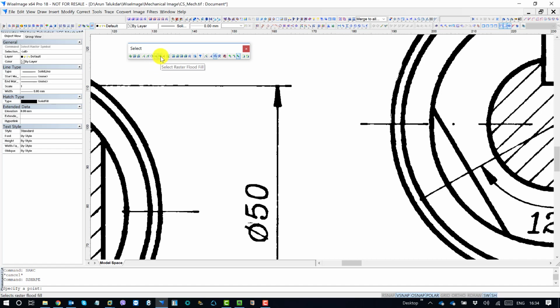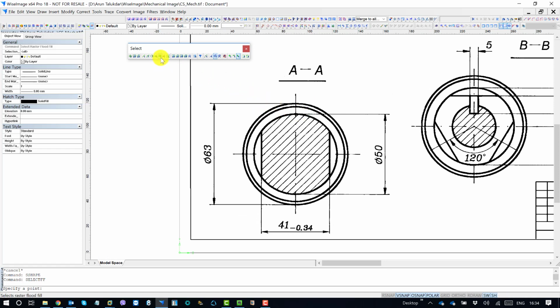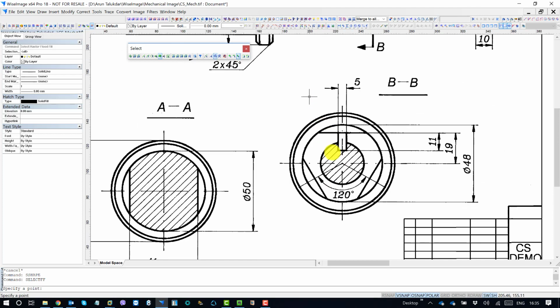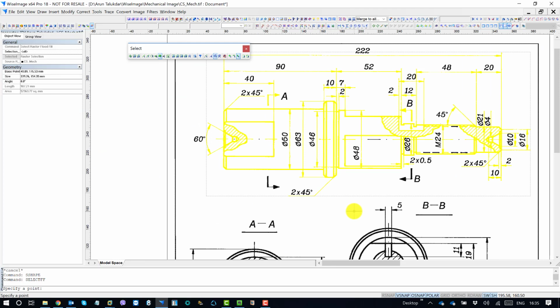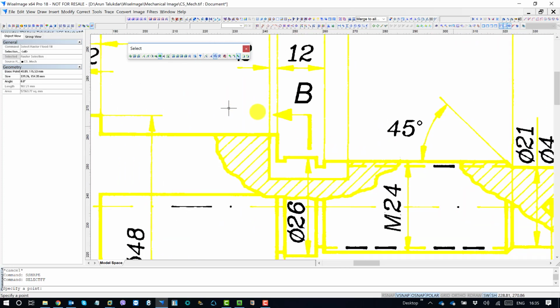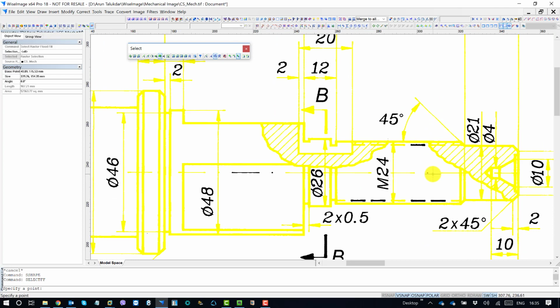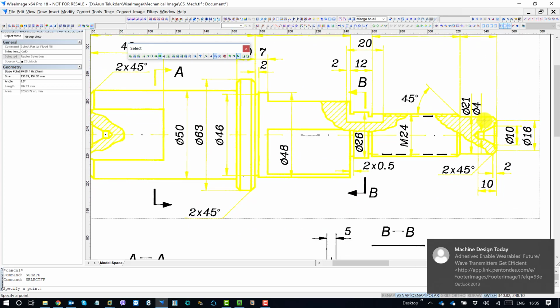And I have this function. This is very useful. You can click on this function. So now you are almost not allowed to do anything except select objects. When you are in the flood fill mode, you can click any of the objects and that will select the whole assembly. Remember, in this selection, all the objects you are targeting to select, you need to verify that those objects are touching each other.